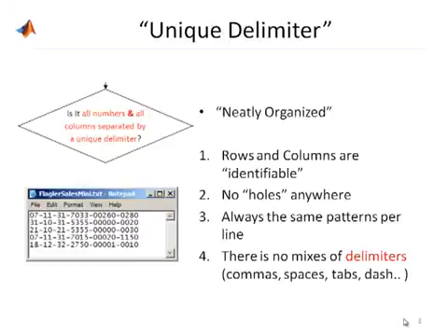Now, as far as explaining unique delimiter, what delimits each column. Here in the example we have a dash. So the delimiter in this file is a dash. More commonly we'll probably have white space or colons or tabs, but this particular file has a dash delimiter. Now, as far as the organization overall, we have 6 columns and they're all neatly organized. There's no holes anywhere. So dlmread is a perfect candidate for this file.